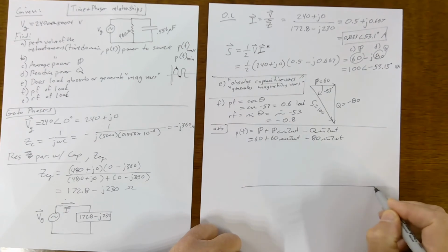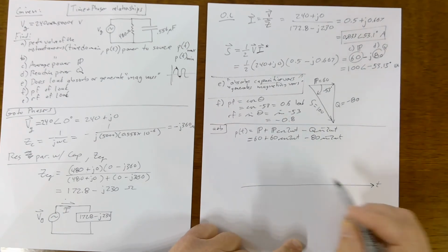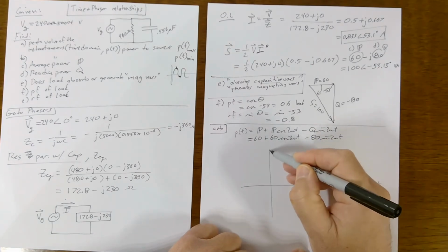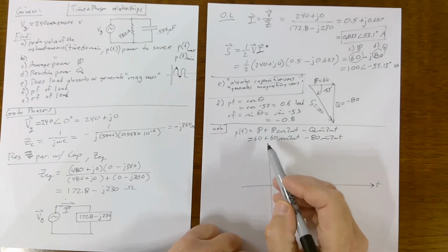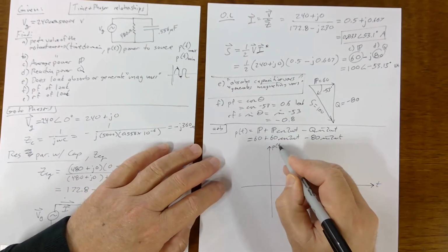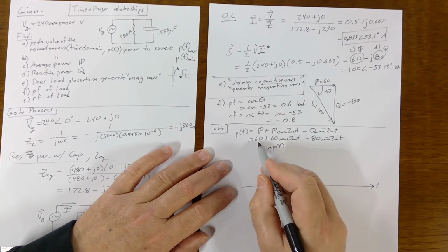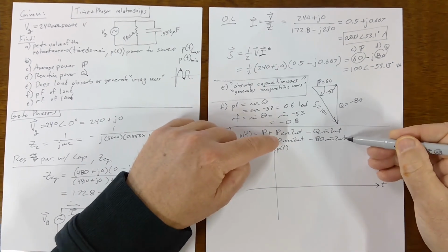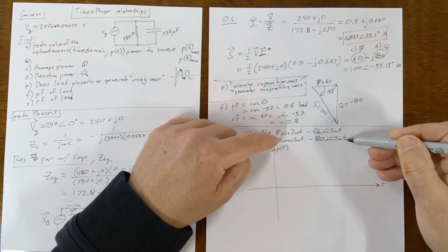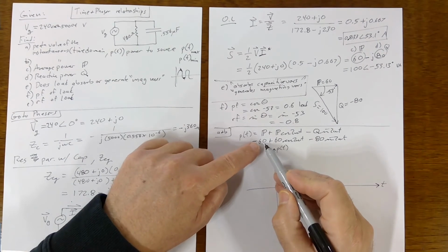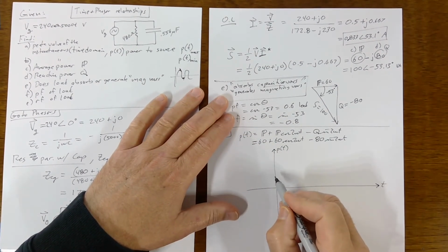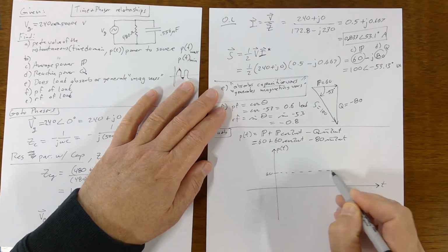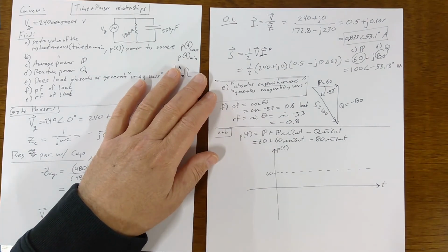The second thing, if you just plot this, you could do some more trig on this and prove things to yourself, which I did, but it's not really worth it. So this is p(t) as a function of time. The 60 out front is going to shift this. The second two terms just add up to a single sine wave, and the 60 is going to shift that up by 60. So at 60, that's the average power, or the real power. That's big P.